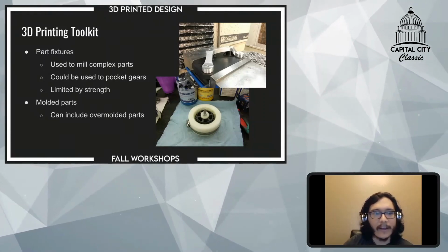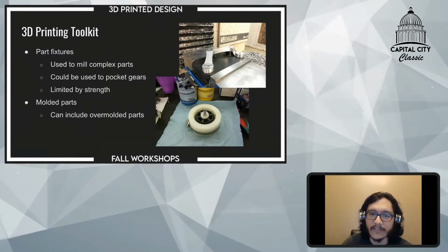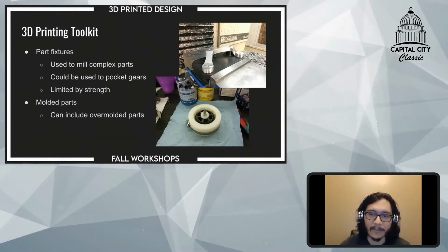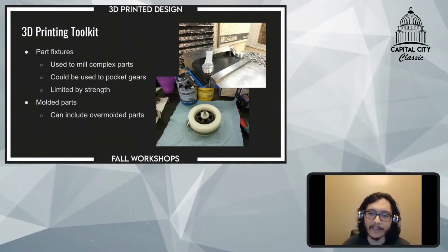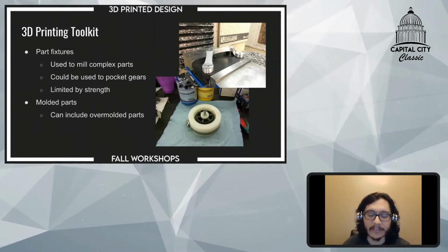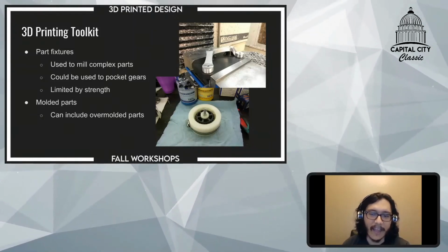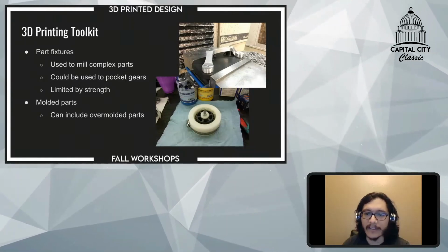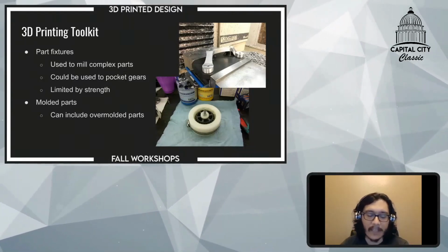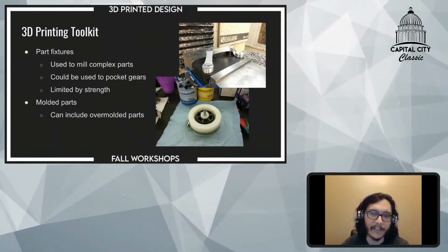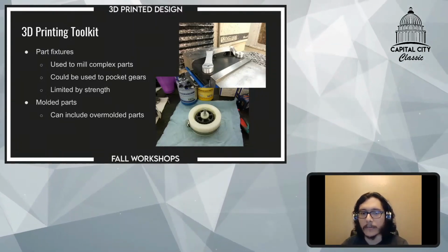And then finally, molded parts. I've seen before, where a lot of COTS parts were available, especially soft rubber wheels, teams would 3D print a mold for wheels and stuff like that, and cast whatever rubbers they wanted. If you can't find a wheel or something off the shelf that meets the criteria you want, this is a good route to go.